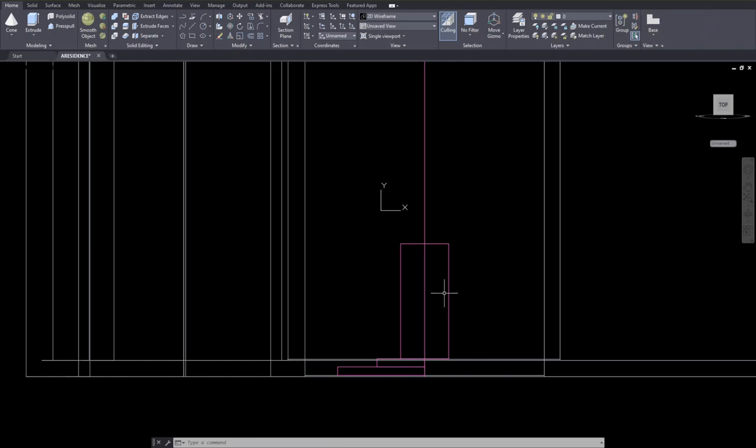Every door comes with a door frame, so we're going to just add a 3-inch door frame, and I'm going to use the offset command for this. The computer is asking me for the offset distance, and 0.03 for 3 inches. Like that. Okay.